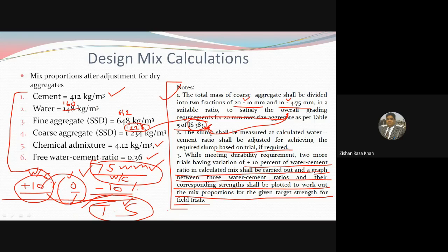if you are doing a rapid curing test, then you need at least 4 days to figure out whether you are designing the right mix design. Okay, and actually if you have time, you should wait for 28 days and find out the actual result. But what happens, because it is a trial mix, you cannot wait for 28 days for every trial mix.